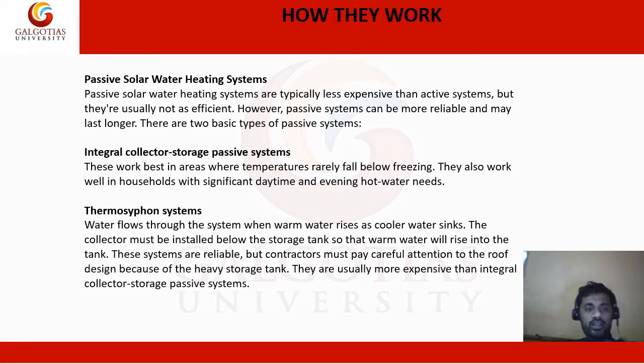Integral collector storage passive systems, as we know, don't require any pumps and everything like active systems, so they work best in areas where temperatures rarely fall below freezing. They also work well in households with significant daytime and evening hot water needs.